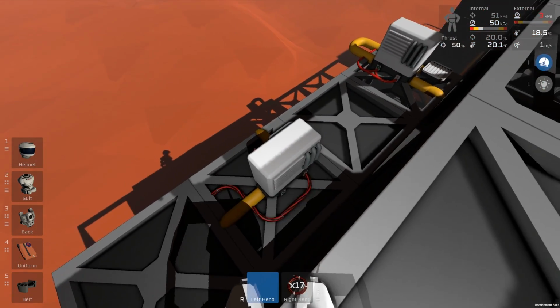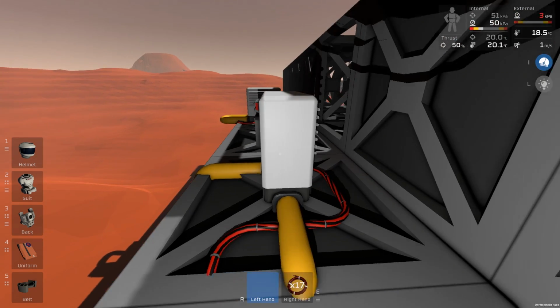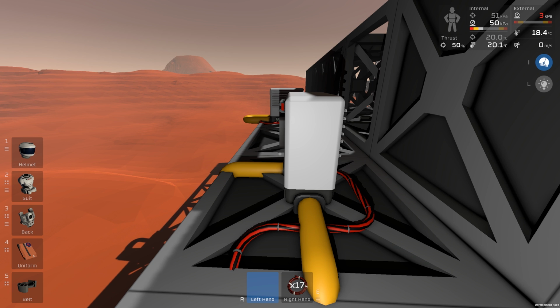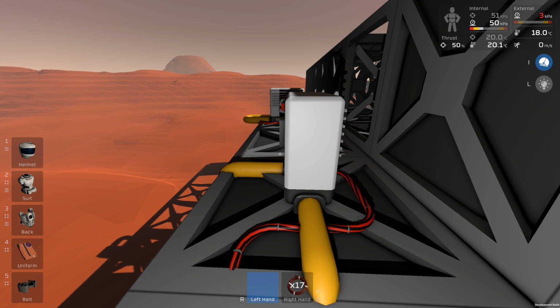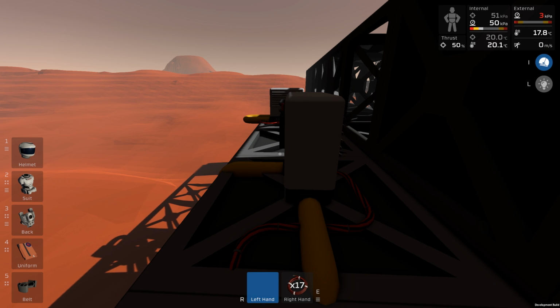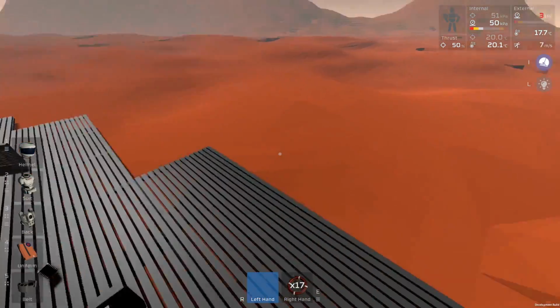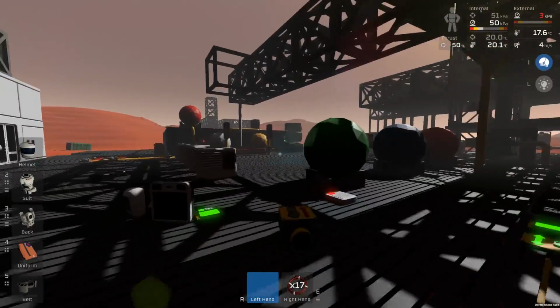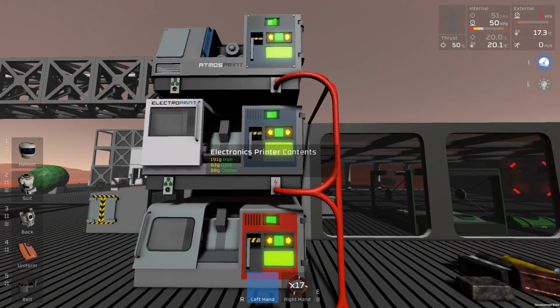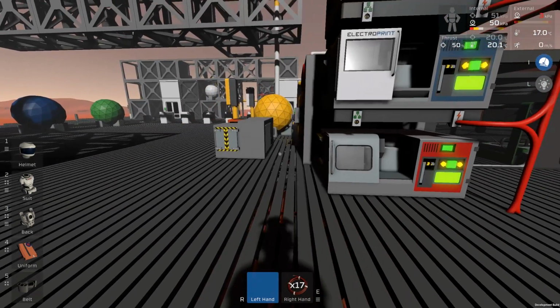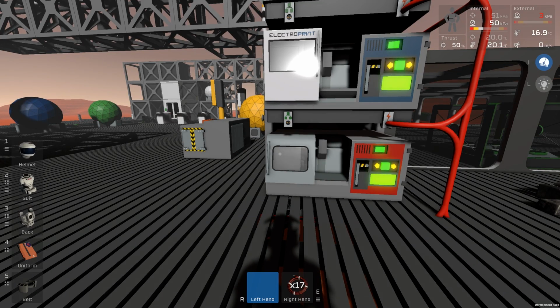To test it, all you really need to do is turn a filter on with... you'd have to put the input pipe with a pressure regulator feeding it quite slowly and have the tank be a certain value to start off with that you're feeding into this pressure regulator, and then you just leave it on. And once the tank empties all the way, you see what your filter is up to. That's my backpack going off. You see what your filter is up to, and then you put a new filter in, refill the tank, and this time just pull the pressure regulator out and put a straight pipe and see what happens. And if it depletes at the same rate, then cool. You know that it's just about the quantity of moles going through the filter.